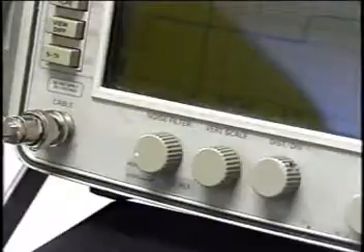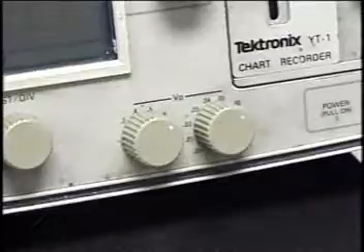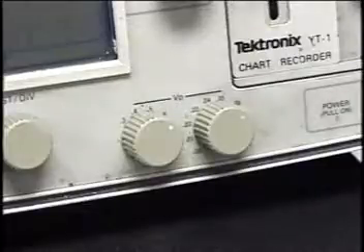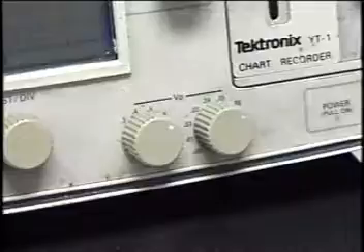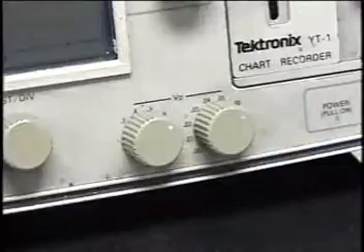The higher the noise filter setting, the more time it takes to stabilize a signal. VP stands for velocity of propagation and is adjusted according to the dielectric of the cable you are testing. The left-hand knob adjusts tenths and the right-hand knob adjusts hundredths. For a cable with a VP of 0.78, you adjust the left knob to 0.7 and the right knob to 0.08.